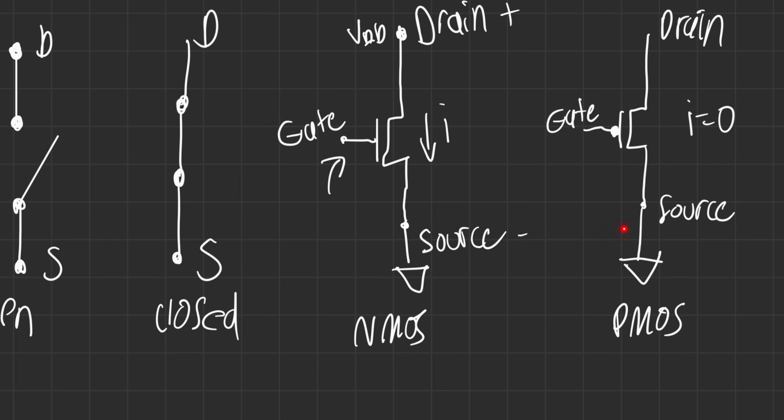And for the PMOS, you apply voltage to the gate, and it actually stops current. And it's the opposite. So in the case of an NMOS, if you do not apply voltage, current goes to 0. And in the case of PMOS, if you do not apply voltage, the current flows. So there's specifics of how much current is allowed and all that sort of thing. But that's very basic. We're talking about this from a digital designer's point of view of what goes where, like which one is it? Maybe this is why you're studying, of like, oh, which one is it? So that's kind of what it is.